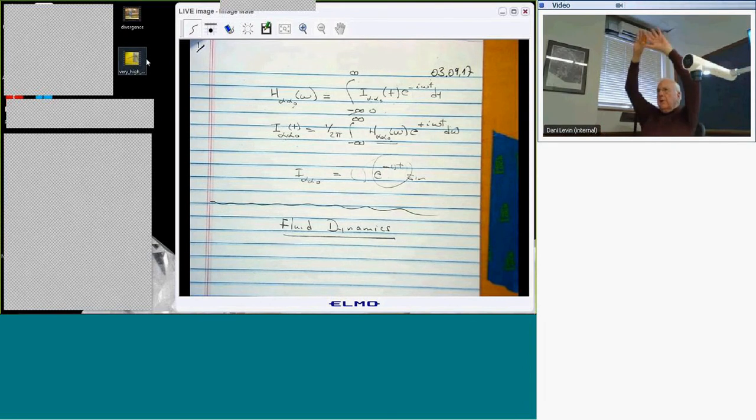But with a fluid, if you think of a glob of fluid and there's fluid coming into that volume, like this room, there's fluid coming in the door, and then maybe there's some fluid going out the door, right? And then there's fluid changing inside. So if you look at a so-called control volume, say the volume of this room, you have to think about the mass coming in, the mass coming out, and the mass change in the room itself. So you have to write down conservation of mass.